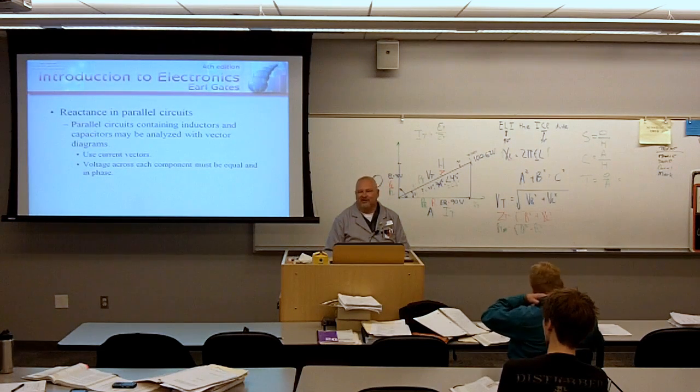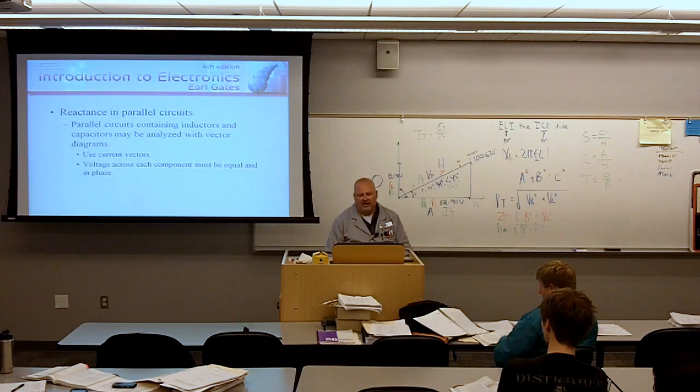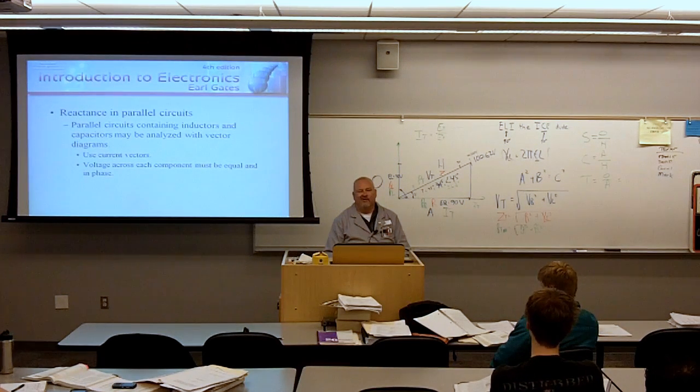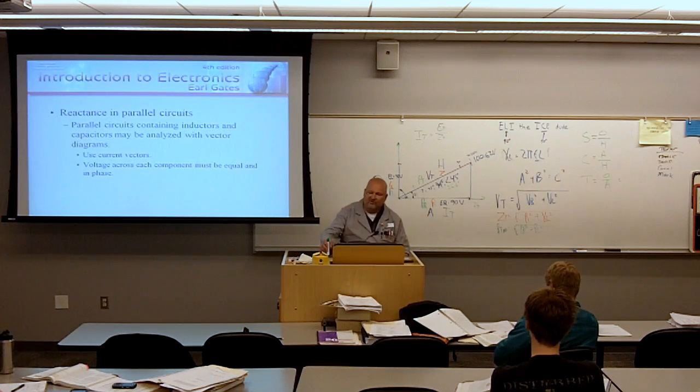Reactance in parallel circuits. Parallel circuits containing inductors and capacitors may be analyzed with vector diagrams. What kind of vector diagrams are we going to want to use in parallel circuits? A parallel circuit is also known as what? Current divider. So what kind of vectors are we going to have to use? Current. Can I use voltage vectors in a parallel circuit? Why not? Voltage is constant. Very good. There is no phase shift of voltage in a parallel circuit. What the voltage is the voltage.